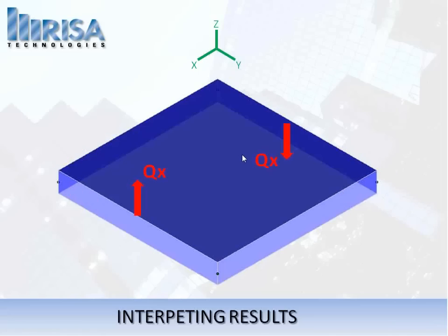Now, aside from those, we also have shears in the plate. This is an out-of-plane shear, and this would be a shear that's running along the local x-axis. That's called the Qx. And similarly, another one that runs along the local y-axis, that's called the Qy. Now, there is no Qxy because shear doesn't have a similar correlating force that goes along like that.